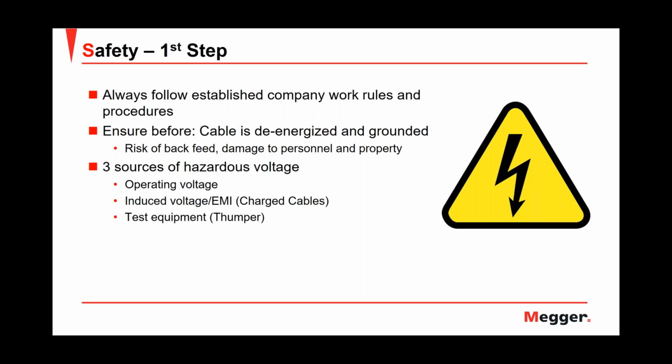The last point to keep in mind is the three sources of hazardous voltage: the operating voltage, the induced voltage, which means the charged cables around my fault location, and the test equipment, which means the thumper.